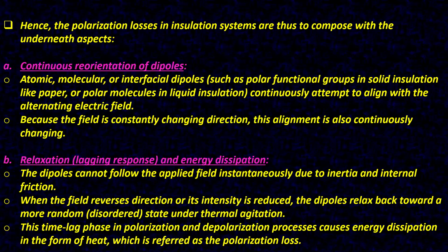When the field reverses direction or its intensity is reduced, the dipoles relax back toward a more random, that is disordered, state under thermal agitation. The time lag in polarization and depolarization processes causes energy dissipation in the form of heat, which is referred to as the polarization loss.